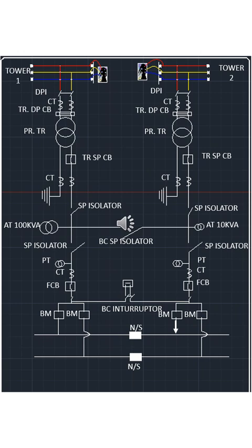Another is delta I. Somewhere the resistive path is too high. Suppose a conductor has fallen on the ballast of the railway track, so it is not an immediate dead earth fault. So a sudden change of current will occur. That will be sensed by the delta I relay, and your CB will trip.